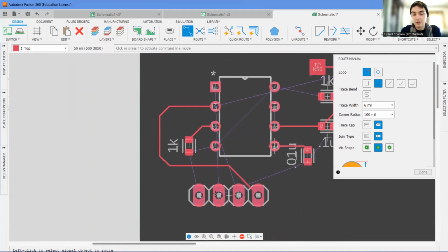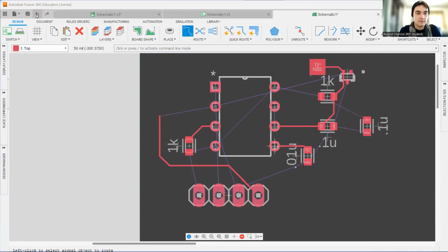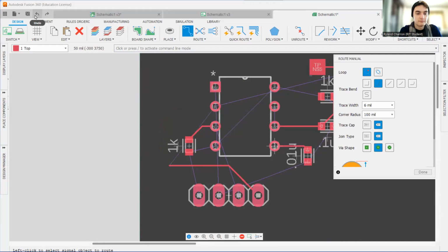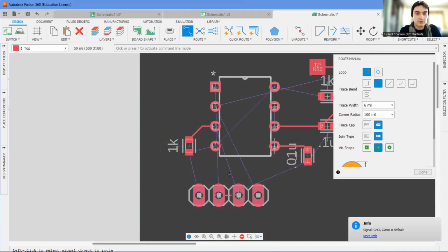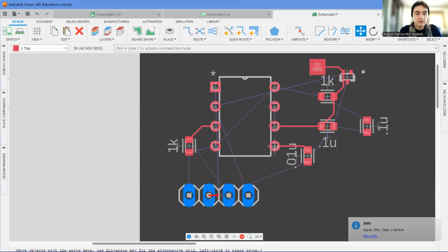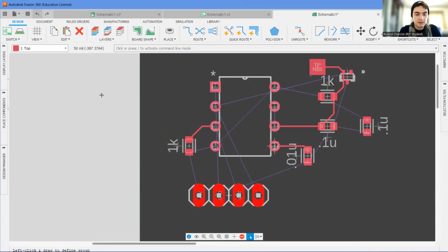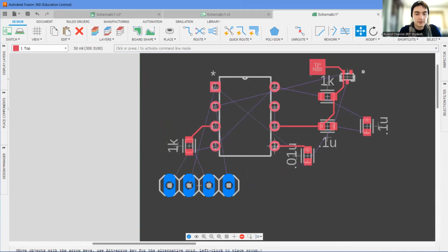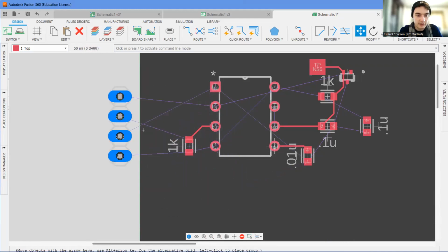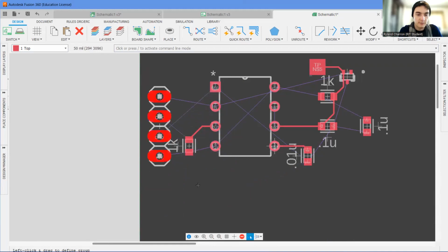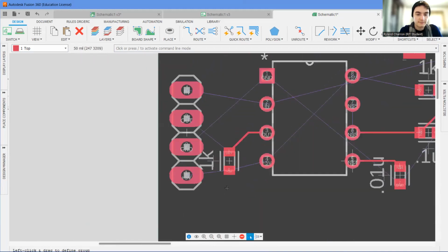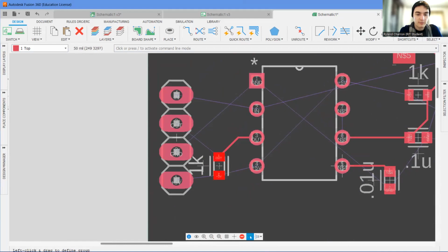Like maybe it would be better if we move the pins over here. So let's try that, because this is a pretty bad design right here. So we're just going to undo that wire. And we're going to move this. Oh, I'm still in routing. All right, grab this. We're going to rotate it, and there. Now it's going to be closer to the pin we're actually trying to get to. Same with the output pin now.